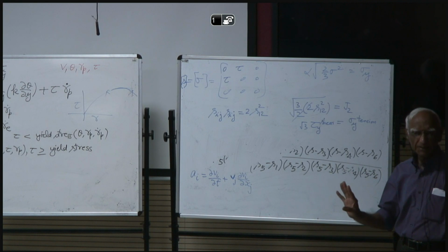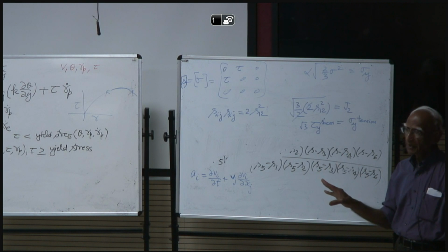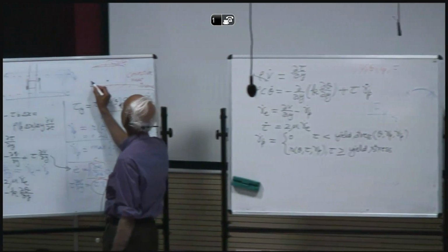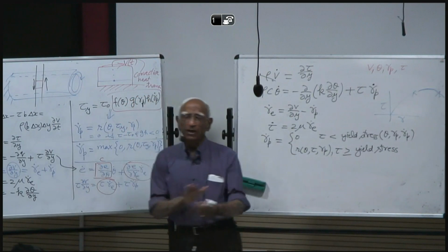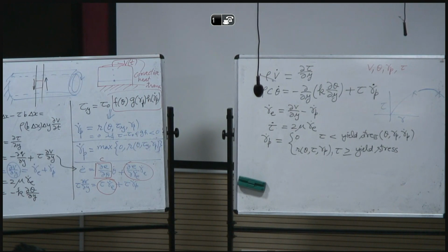Remember, this is a simple shear problem. But if you do a complex loading problem, then things are different. In this case, because it is shearing this way, once it starts sliding, there is not much to prevent it from going faster and faster. But if you are doing a 3-dimensional problem, and there is a local defect or softening inside, there is a lot of material around it that can prevent it from propagating throughout the structure.